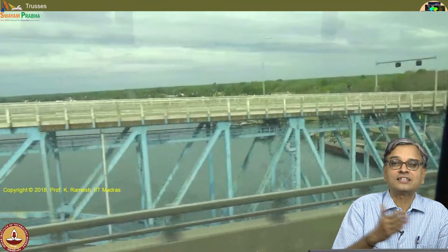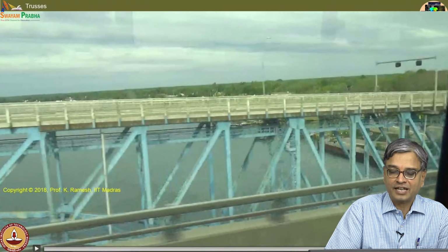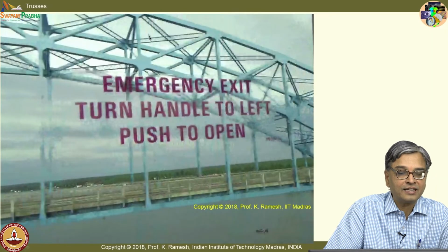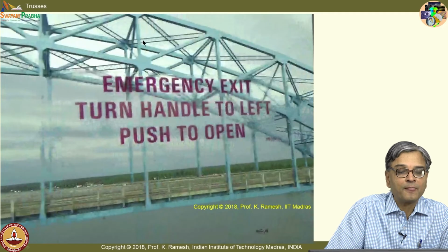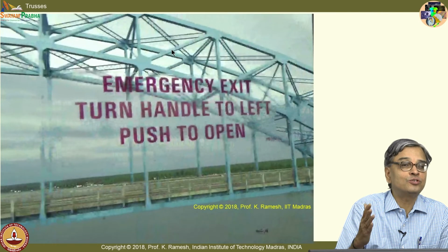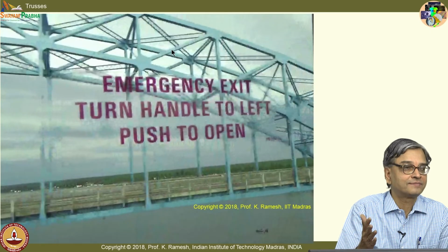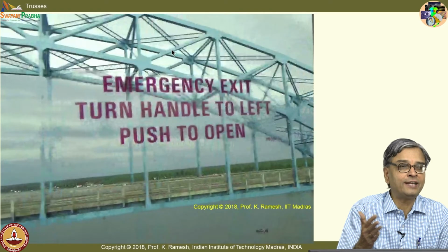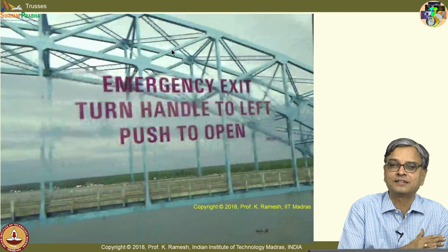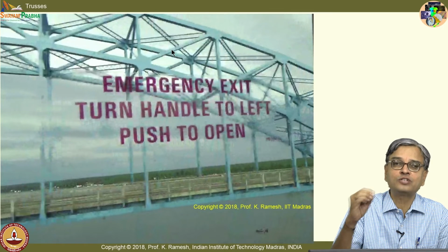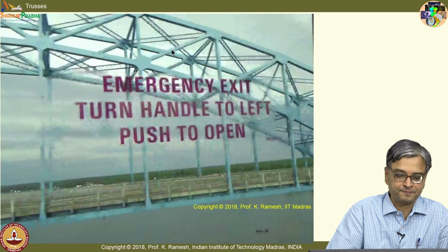This is just crossing that bridge, and here again you could see the cross bracings to prevent damage due to wind loading. The resonance was precipitated mainly because of wind loading. So, people have learned from experience and they have accommodated this wherever in the future designs that they have employed.